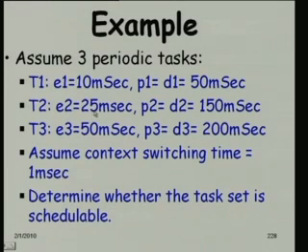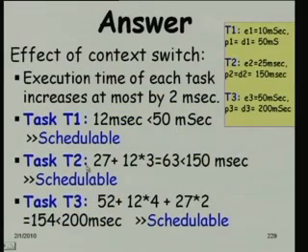Those context switches are taken care of by the higher priority task. We are factoring in those context switches here, so considering just 2 for this is all right. Similarly, for this task, we will factor in the context switches due to T2 and T1. Now, let us see the solution.